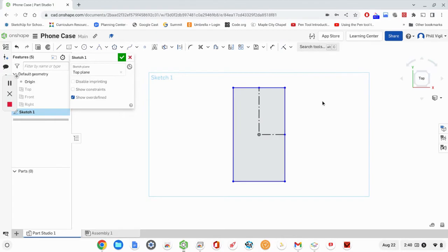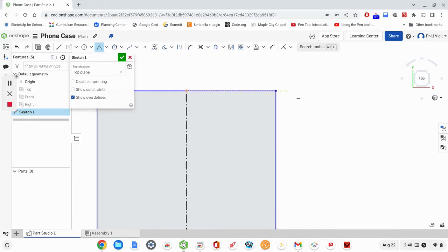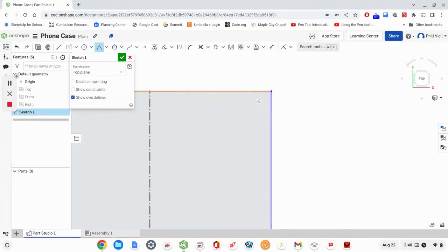All right, now we're going to make a corner arc. So it's going to round off our rectangle, and we're going to use the conic option. And we're going to just find a spot here in the corner and attach it to the horizontal line at the top, and then the vertical line on the side. And then the virtual sharp is the thing that stretches out the arc. We're just going to place that somewhere. Well, actually, we're going to attach it to what would be the corner of the rectangle. So click there to attach it, and then enter to accept the 0.5.